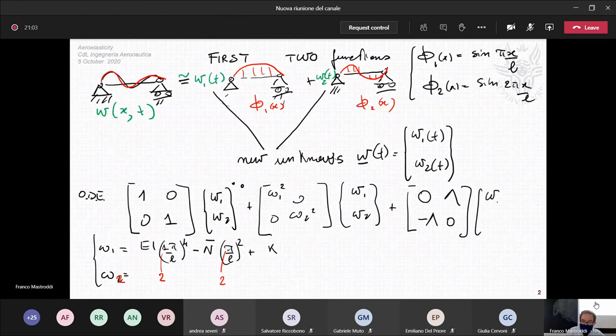So for this kind of physical system, once you discretize it, you have 2 stiffness contributions, one standard diagonal or symmetric, the other one skew symmetric, as given by the aerodynamics. Moreover, at the end, you also have a damping contribution as a final part of our model. We have a diagonal damper, zeta 1, 0, 0, and zeta 2.